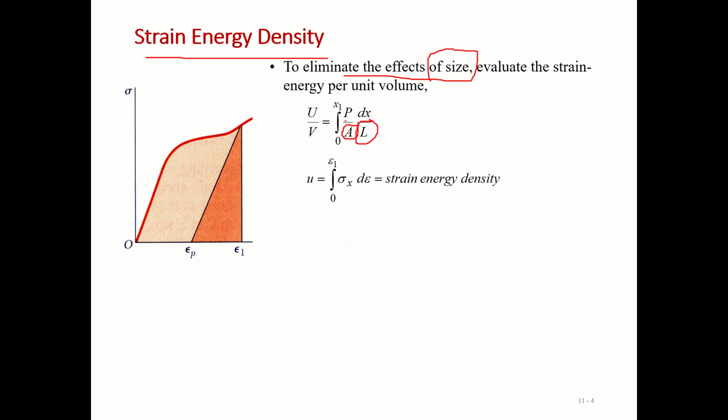So P over A is the stress, and dx over L is the strain. So strain energy density is equal to the stress multiplied by the strain, and we will integrate for the whole curve. This is the strain energy density.